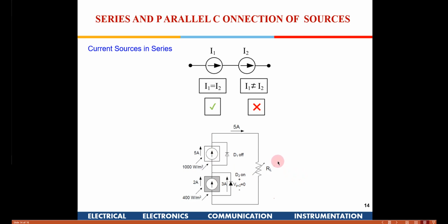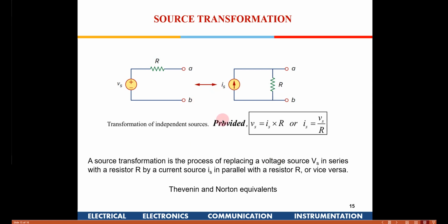So these things will be slightly different. We will learn these subsequently, but I am just covering this slide here because in the tutorial, otherwise, based on power sources we will have very few problems. We will discuss how this has come in later classes, but just understand this formula so that it becomes easy in the Monday tutorial, where a voltage source with Vs and R is equivalent to a current source with an R in parallel.